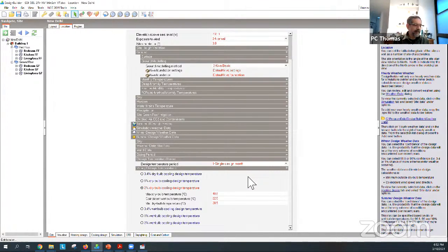Okay. Now, you can see here, I've got 6 options, right? And I've selected a single design month, right? So I've got what are called dry bulb priorities. So it looks at the temperature and then says what is the coincident humidity at that time for design condition.